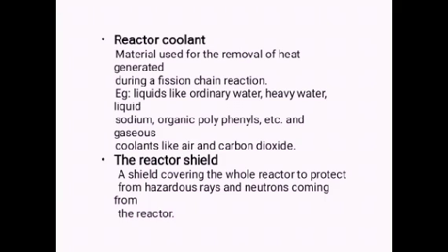It absorbs much of the gamma rays coming out of the core and protects the outer shield from possible heat damage. The second one is the biological shield, capable of absorbing both gamma rays and neutrons, and usually consists of a layer of concrete several feet in thickness surrounding the core.